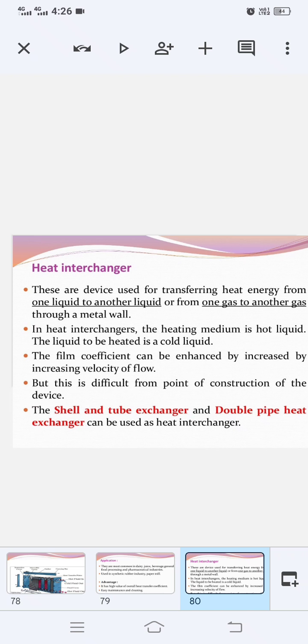Two pipes are used, one inserted in the other. The inside pipe is used for pumping the cold liquid to be heated, and the outer pipe acts as a jacket for the circulation of the hot liquid. All the jacketed sections are interconnected. Normally the number of pipe sections is very few. The length of the pipe is also less. Glass tube, standard iron pipe or graphite constructions are available for the pipes. But standard metal pipes are assembled with standard return bends.